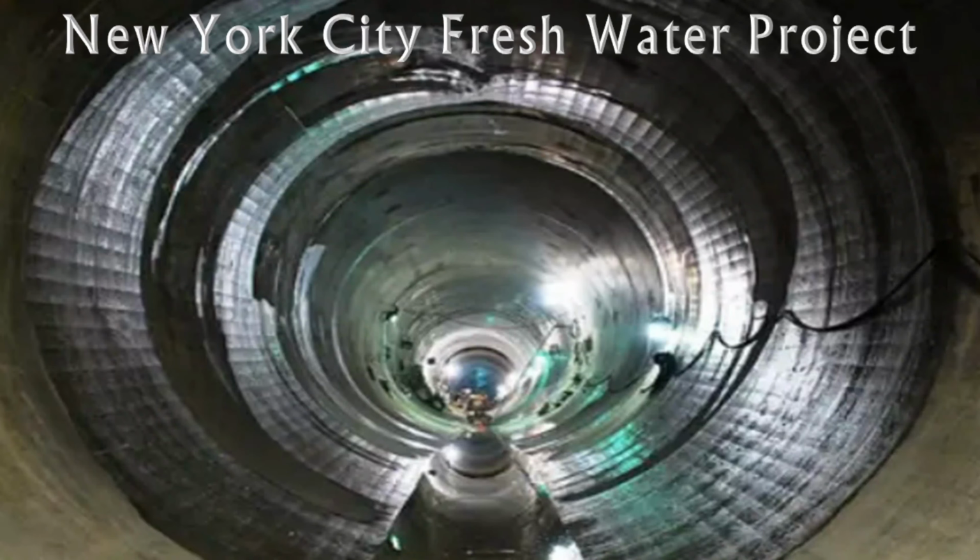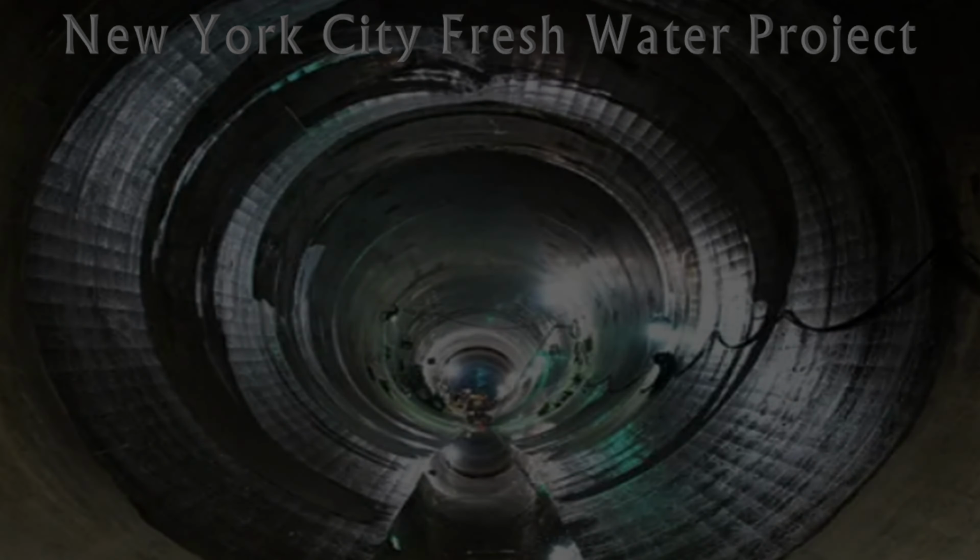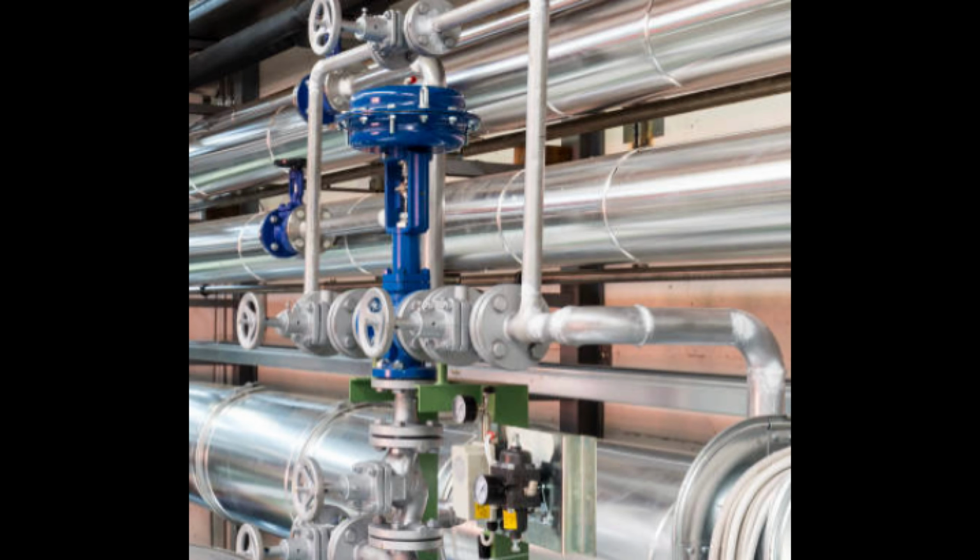Well, how do you get valves and pipes and things to last 100 years under the ground? Well, the whole system will be manufactured from stainless steel. Actually, if you really look at what they're putting in there, which is a 316 stainless steel, barring an earthquake or a nuclear attack, that freshwater system will probably be there for many hundreds of years. The corrosion resistance of 316 is pretty phenomenal.